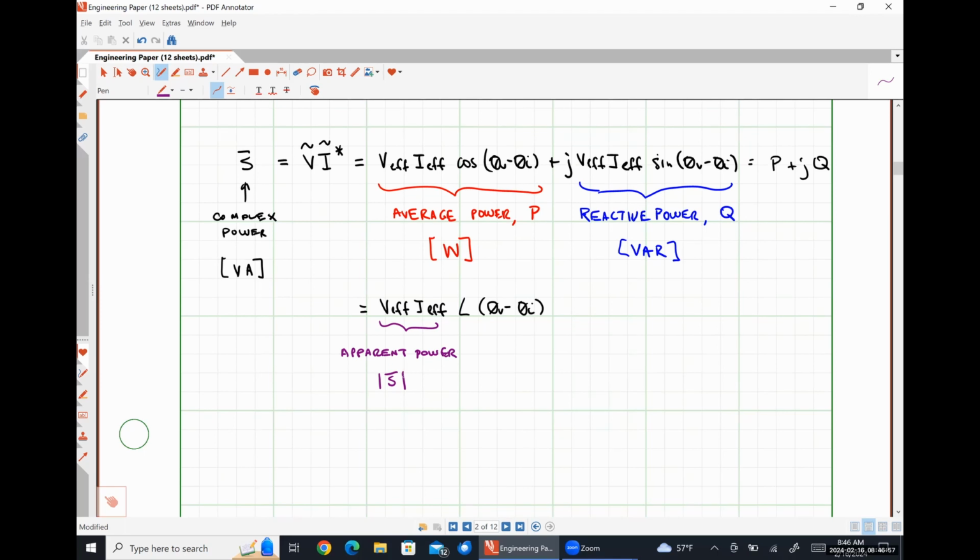I don't know how many of you have ever had to look into purchasing an uninterruptible power supply, or maybe help the parents buy a generator for their house. But typically they have 2 different ratings. One rating is in volt amperes, that's the apparent power it's rated for. And the other rating is measured in watts, which is the average power it's rated for.